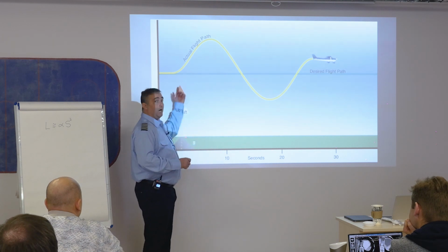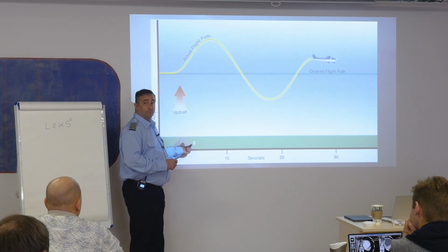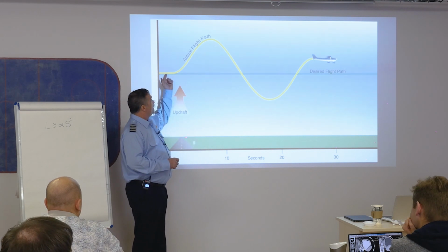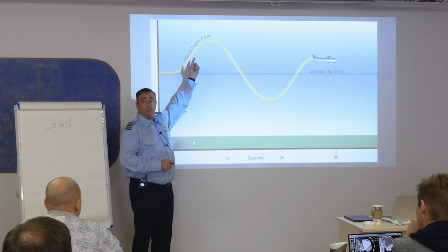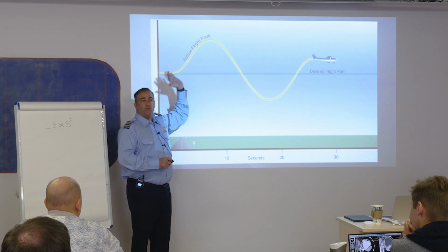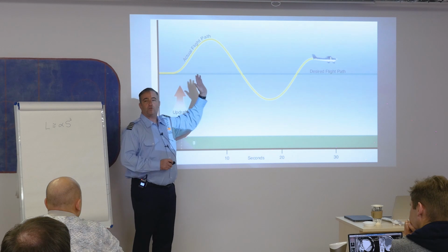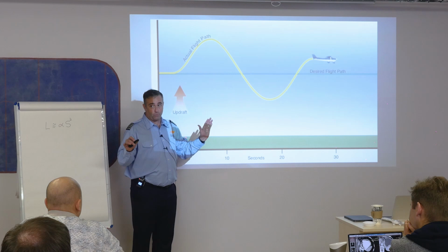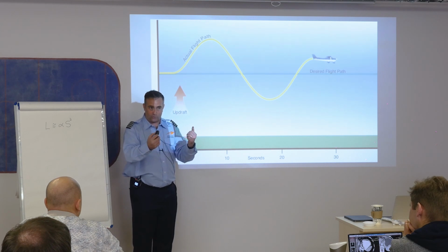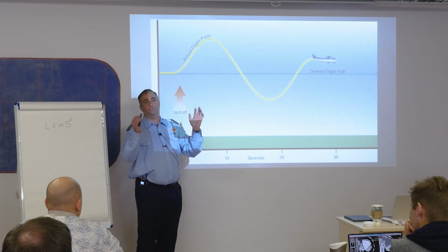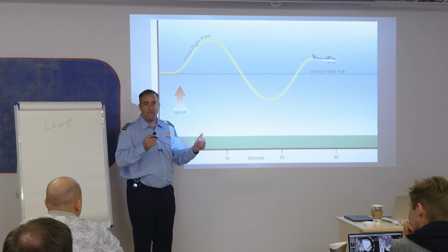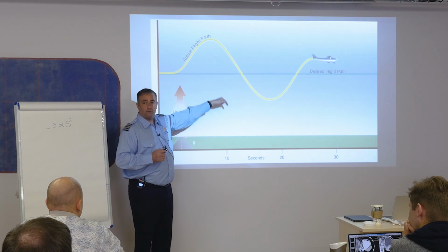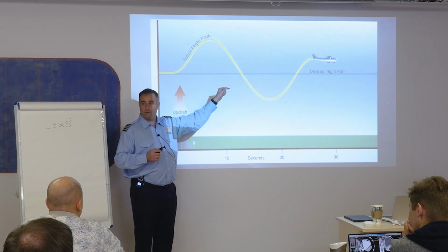Okay, so I get a little updraft by this road. Some convection that causes the airplane to move upward. If I don't touch the flight controls at all, okay, which is okay, I've got control of the airplane. I'm not letting them go completely. But if I don't apply any pressure at all here, the airplane will naturally return towards the desired flight path.